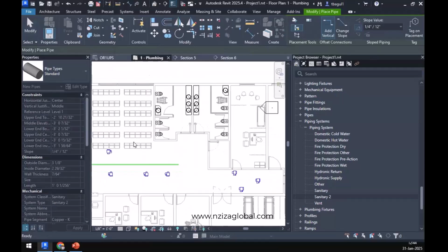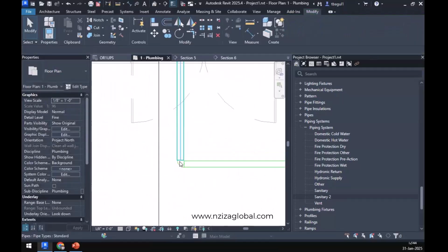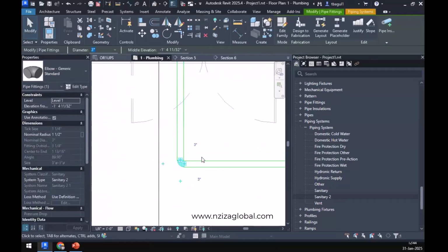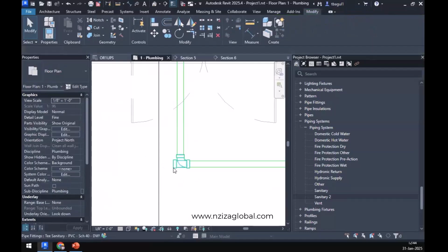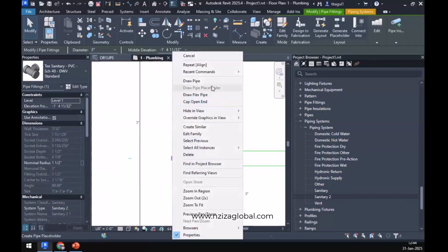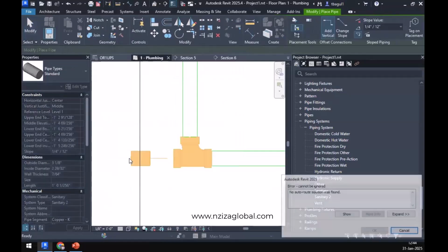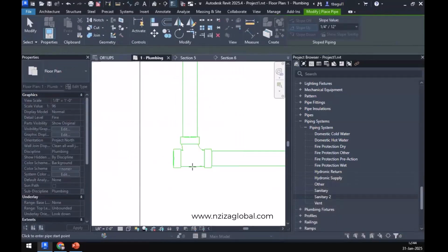Okay. When we are doing a turn in a given plumbing system for sanitary, always make sure you have a clean out. If it goes a 90 degree, make sure it has a clean out. What that clean out is basically is, just a minute, I'll come to your point.